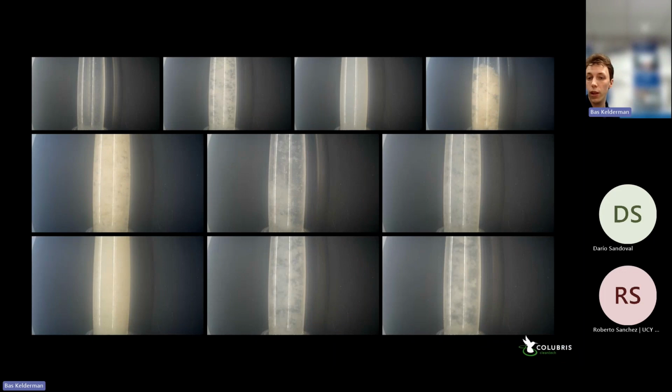And of course, anything in between that is also something we need to consider. So here you have a number of pictures where coagulation does seem to be taking place, but it's not flocking too well. Perhaps the dosage of the polymer is incorrect, or the pH, or we are just not quite at the correct dosage of coagulant, so we need to increase a little bit more, but we're getting there. These kinds of profiles, where if you look at a picture like this, it's quite easy to see what's going on, are pretty difficult to get out of a sensor.